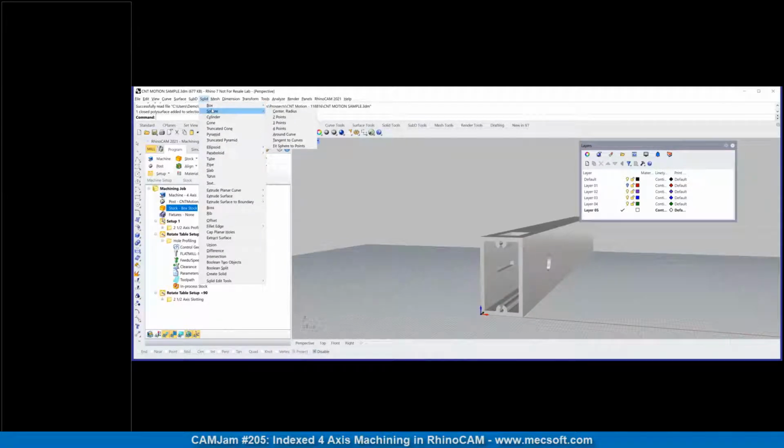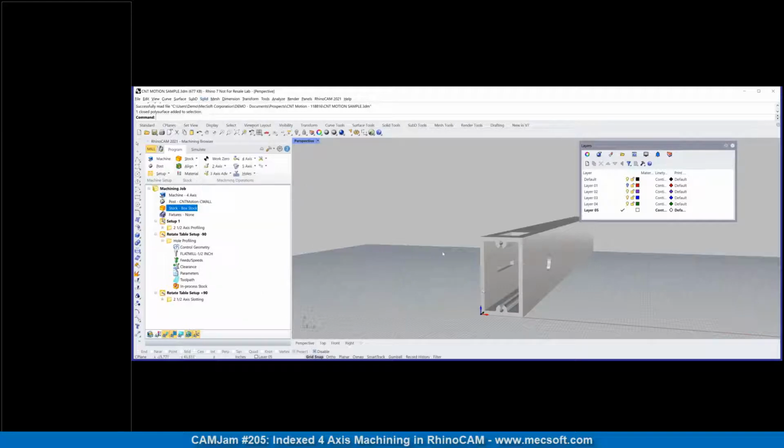If you have the cross sections, just select the cross section, and you can do an extrude solid, extrude planar curve, and then you can do a straight section. So very quickly, I can show you that. Let's say I create a rectangle. Let me do object snap. I'll start at the end. I'm selecting the object snap.